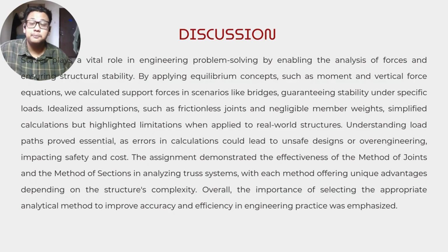Okay, for discussion, statics plays a vital role in engineering problem solving by enabling the analysis of forces and ensuring structural stability. By applying equilibrium concepts such as moment and vertical force equations, we calculate forces in scenarios like bridges, guaranteeing stability under specific loads. Idealized assumptions such as frictionless joints and negligible member weight simplify calculation but highlight limitations when applied to a real-world structure. Understanding load path proves essential, as errors in calculation could lead to unsafe design or over-engineering, impacting safety and cost.